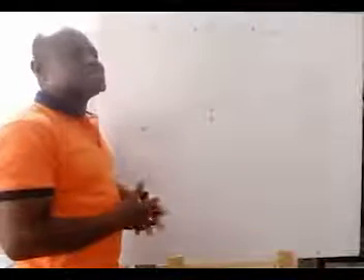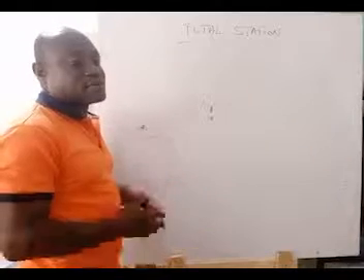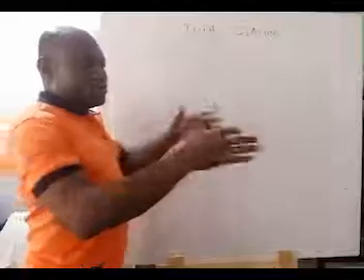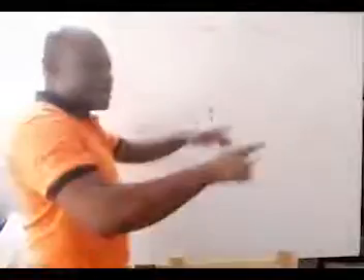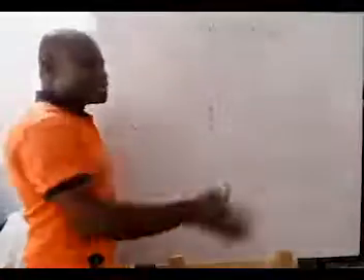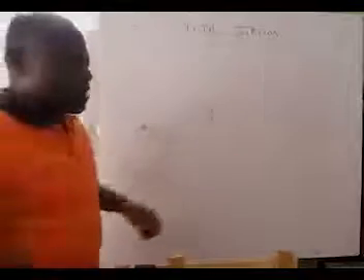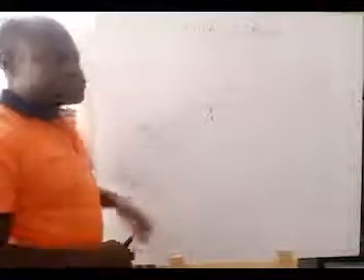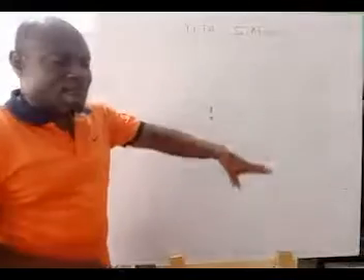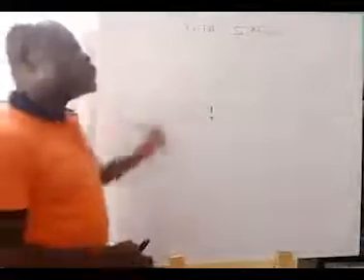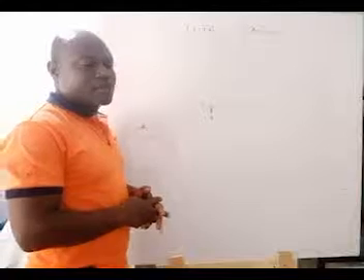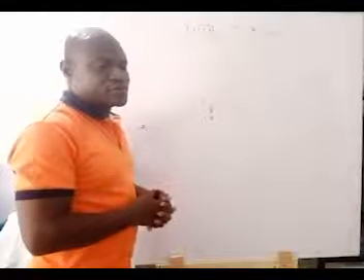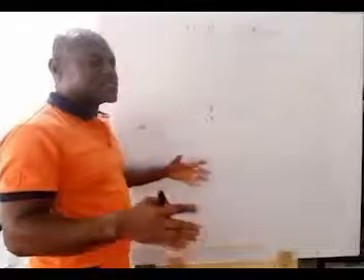You can also use it to set out grade lines on site. So maybe for a small building, you want to do a wooden profile around the building that will have all the grade lines. So you can pull ropes, you can pull lines, okay, to mark out walls, mark out excavation lines and all that. You can use the total station to set the centers of all the grade lines on the wooden profile board, and then from there you continue, and that will make sure the building is properly squared.